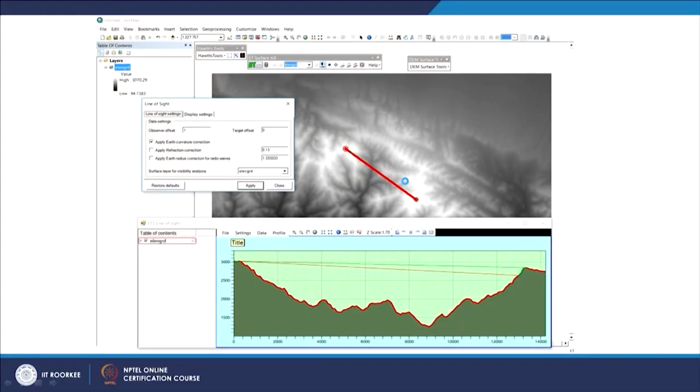The best part here is that things can be done and various possibilities can also be tried, and obviously things can be done very accurately and quickly. Using simple topo sheets or any other technology, it is not possible to do either viewshed analysis or line of sight analysis. Another example here, which you are seeing of ArcGIS, is that there is a line and then there is a topographic profile along this line, and if I am not adding any offset, then only this much area is visible, but if I add an offset, then maybe a large area would be visible.